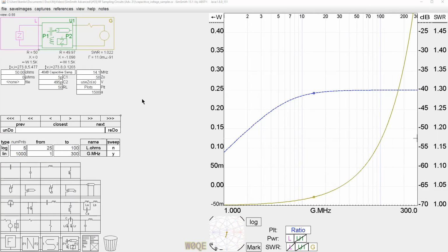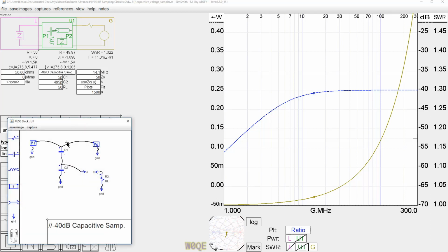The next circuit we have to look at is a capacitive voltage divider circuit. And the capacitive voltage divider, much the same as the resistive voltage divider, uses two components whose impedance is not fixed, but it tracks with frequency. Therefore, the percentage you have right here of voltage, an open circuit voltage here versus what's on the line, will remain constant with frequency. However, if we drive a 50 ohm impedance with it, we see that the coupling factor doesn't stay the same with frequency.